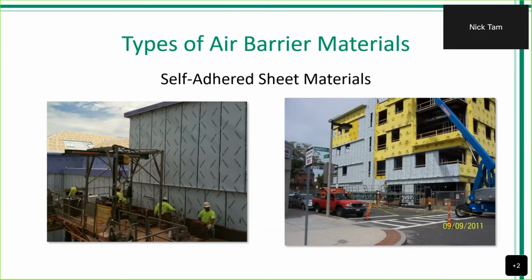But a lot of people ask, what is the point of using this when there's other materials such as fluid? Well, with self-adhered sheet membranes, you're getting a controllable thickness, and they're not going to be at the mercy of the subcontractor to install it at the thickness that we need. And so really when we observe these materials on a job site, we're really just trying to make sure that they're detailed appropriately and that they're smoothly applied without any breakage or any folds or wrinkles.